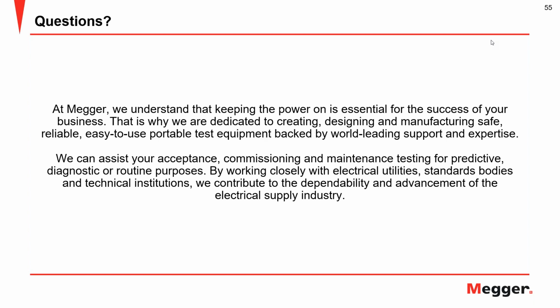There are several reasons for that. DC testing is okay for paper lead cables, so for oil-filled cables, because the oil is the insulation medium. It's partially self-healing, so the DC stress doesn't cause any lasting negative effect on the insulation.